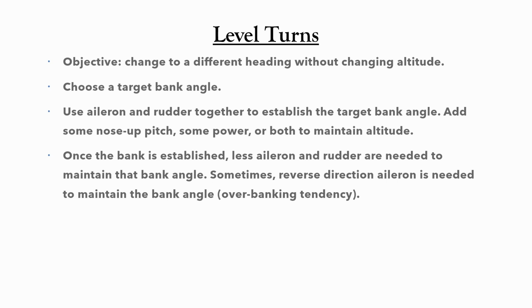Once you've established the bank angle, you'll need less aileron and rudder to maintain that bank angle. In fact, quite often, you'll need reverse direction aileron in order to maintain that bank angle because of a tendency called the overbanking tendency.